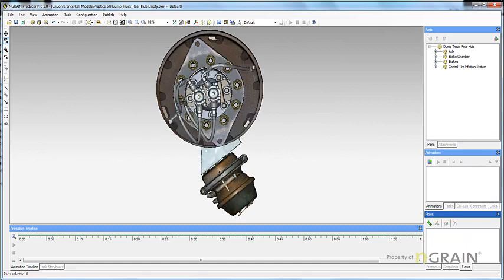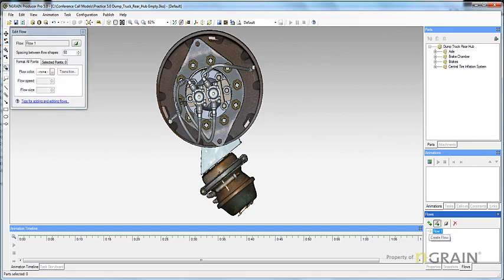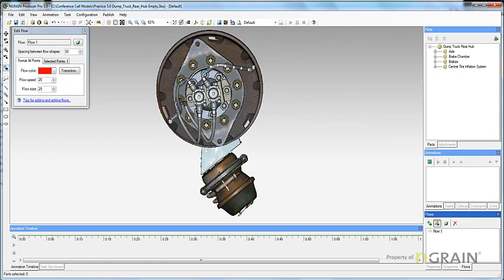The flow panel is located on the right-hand side. From the flows panel, you can create a flow by adding a series of points to the virtual equipment to create the flow path. You can show flows in animations, tasks, snapshots, and the startup snapshot. To start, in the flows panel, select Create Flow. A panel will appear. Start the flow by laying down points. Spread the points out to the desired location.